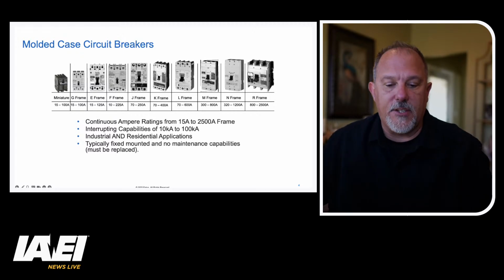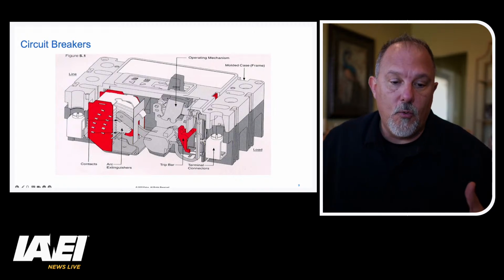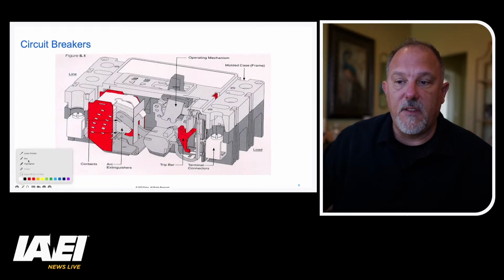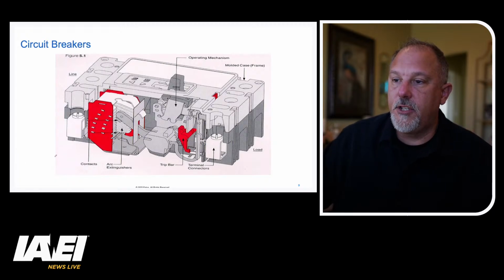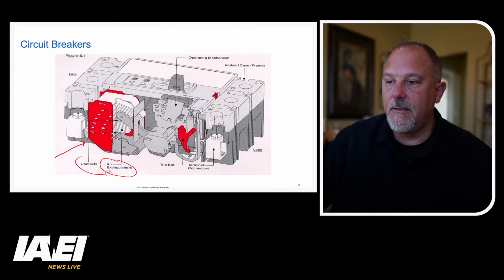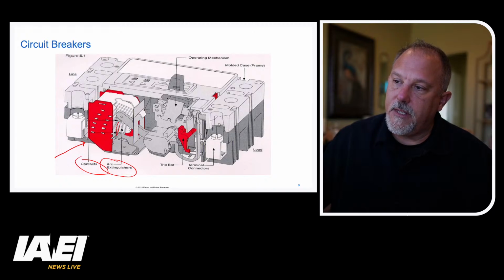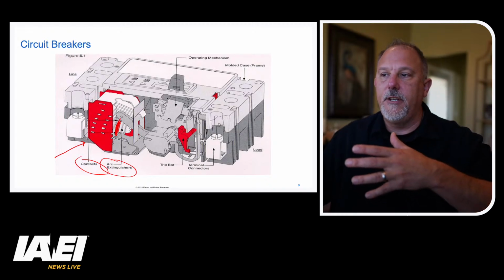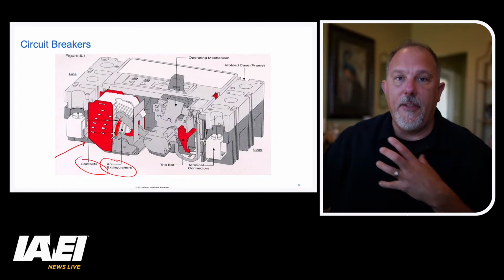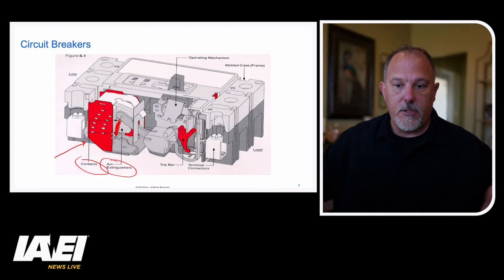How does a circuit breaker do what we say it's going to do? We have a complete mechanism in here, but the important parts to think about, here is your arc extinguisher, right? So you have your arc extinguishers. You have the contacts. This separates, and you'll have an arc being drawn between these contacts, and the arc extinguishers basically divide and conquer that up. So all of this mechanism has to hold it together while it's clearing the fault.